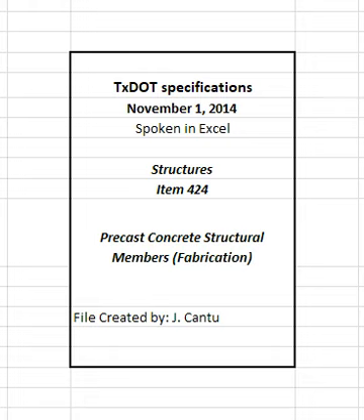Provide a title block on each sheet in the lower right corner with the following information. Sheet index data shown on lower right corner of the project plans. Sheet numbering for shop drawings. Name of structure or stream. Name of owner or developer. Name of fabricator or supplier, and name of contractor.